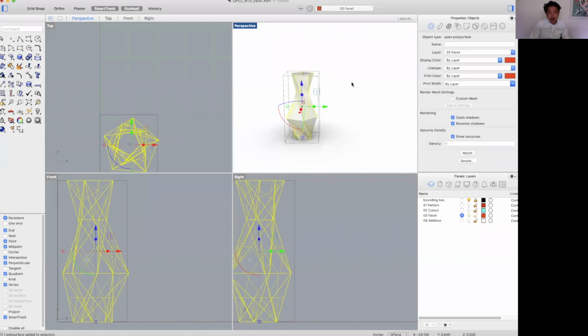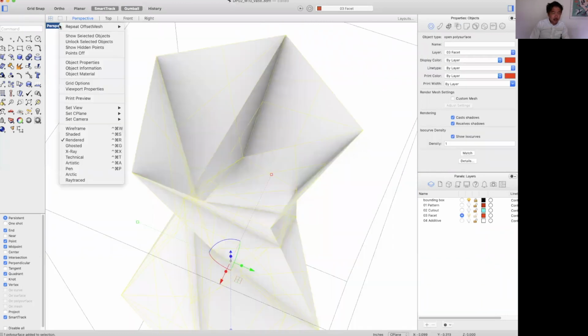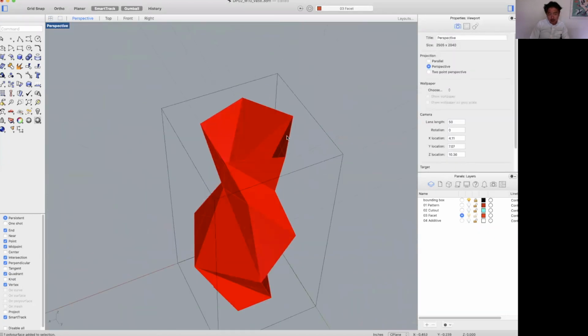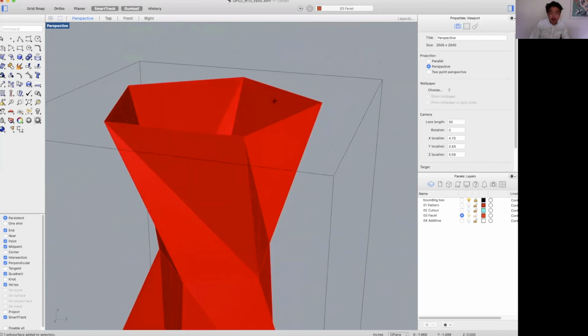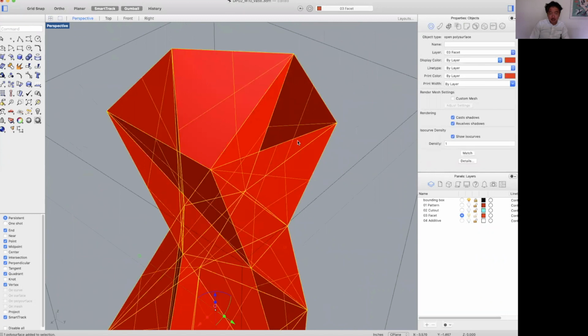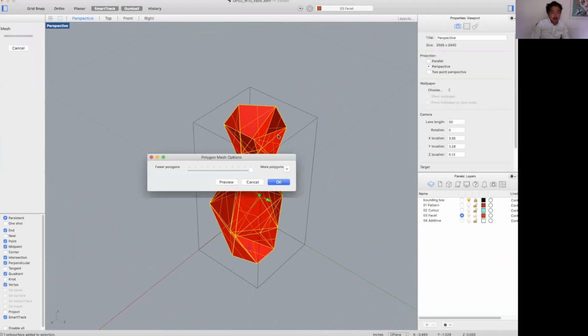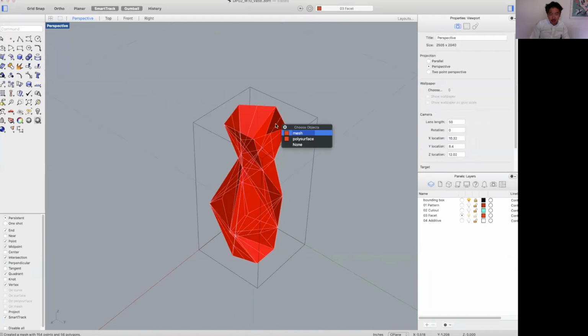So to make this kind of polysurface solid, the offset surf command is going to create a bad result. So in that case, you can actually mesh this object already, which you're going to have to do later anyways. So type mesh, and there it created a mesh object in the same location.